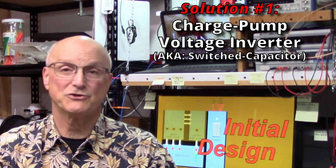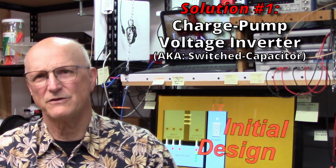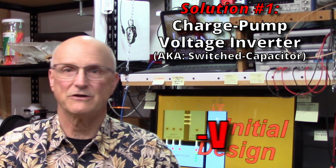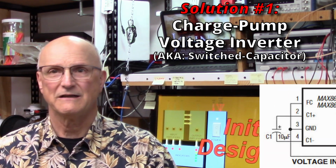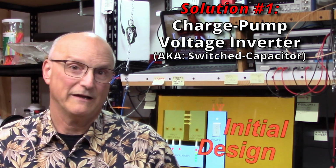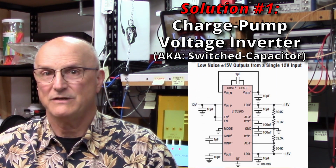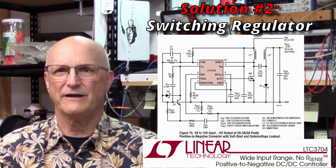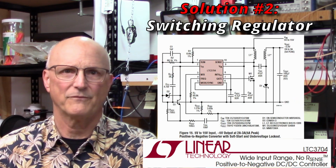Well, there's a few solutions to this. And one of these solutions is what's called a charge pump voltage inverter chip. This takes a positive input voltage and turns it into a negative voltage, like the MAX860. Or even a dual regulated version like the LTC3265. The other option is a genuine switching regulator, which will do the same thing.